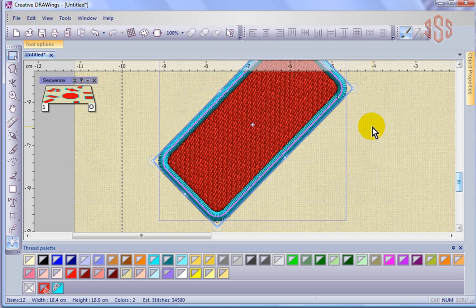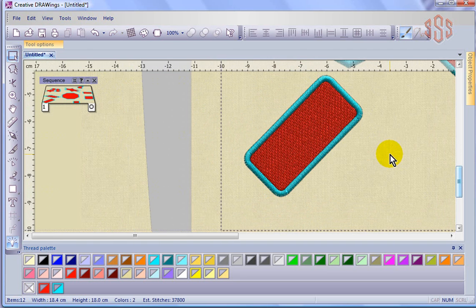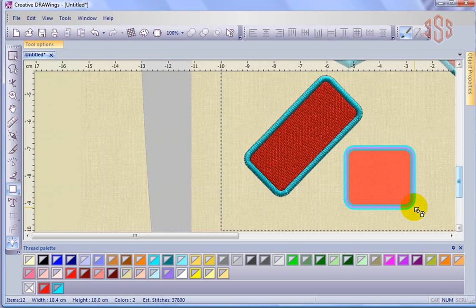So that's using the Control key. Maybe I'll zoom out and grab my rectangle tool, and show what happens if I hold the Control key down while I'm designing. I'm going to left click and drag to start my shape. Now I'm going to add the Control key, and can you see on my screen how I have this set of rays starting from where I started, the first point of my shape, and they go by 22.5, and I can use that.